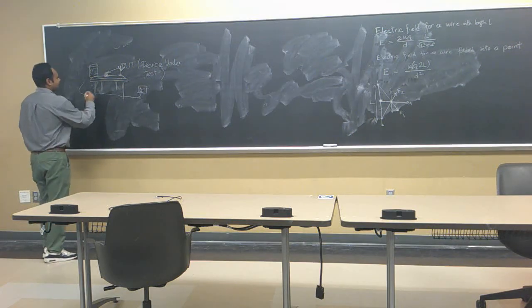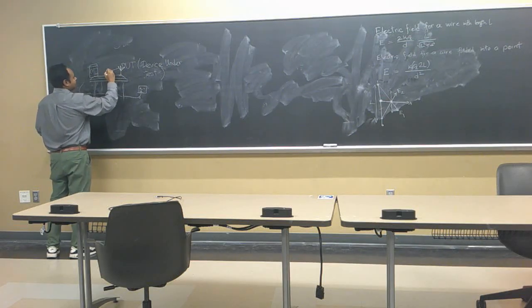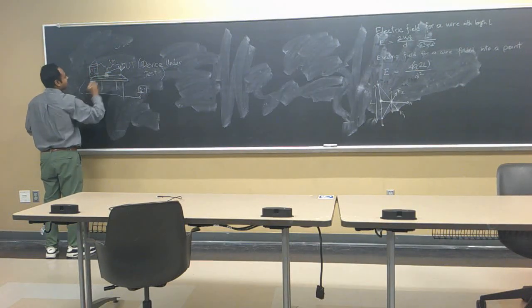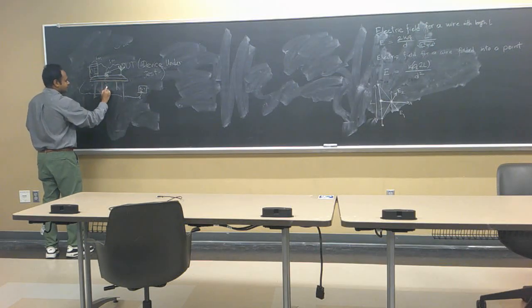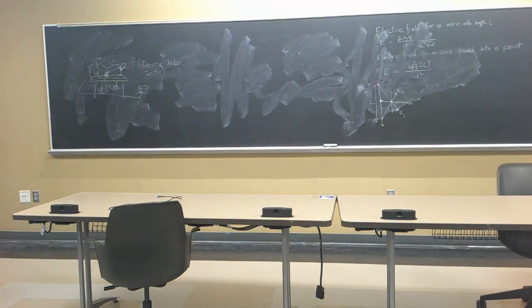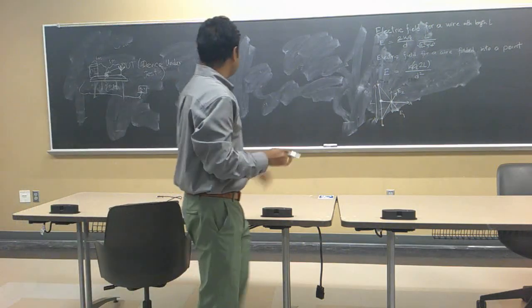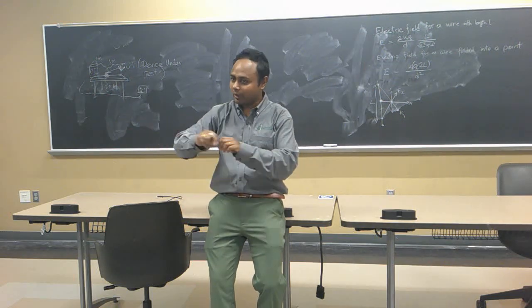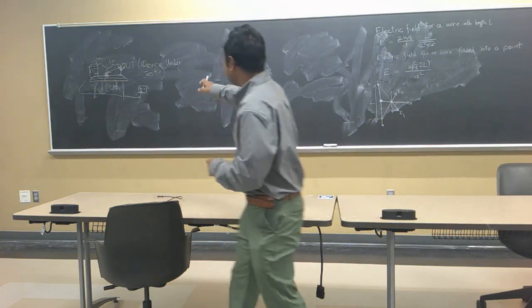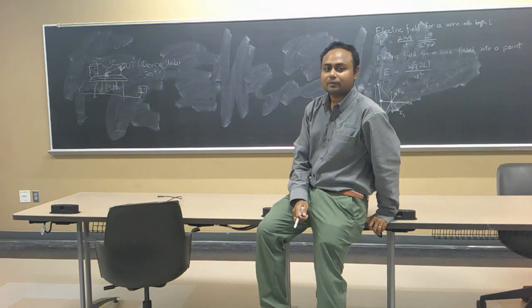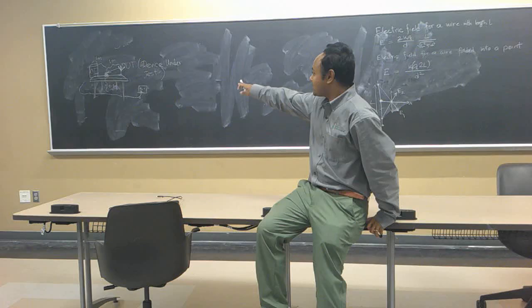So let us say that this guy, let me draw some distance information, okay? So let us say that this is 1 meter. This guy is also say 1 meter, okay? And the distance between that and this cable is probably 0.1 meter. Okay? Again, I'm trying to show you the distance between the duct and the other possible sources of noise. There are 3 possible sources of noise. One is the antenna, one is this microwave, and one is the wires that are running behind the table. Okay? And I told you what the distance is for each of them. So which one would you think the biggest source of noise would be? The wire. The wire, because the wire has the smallest distance.